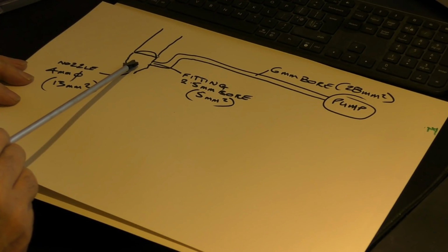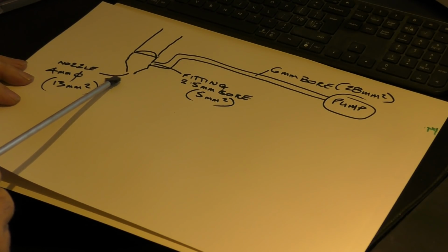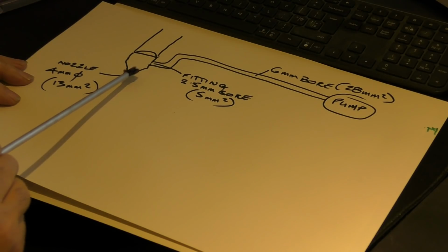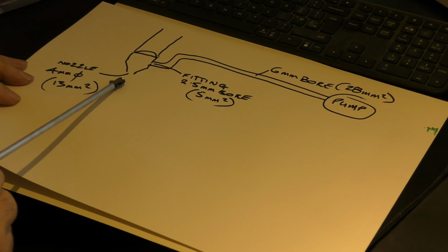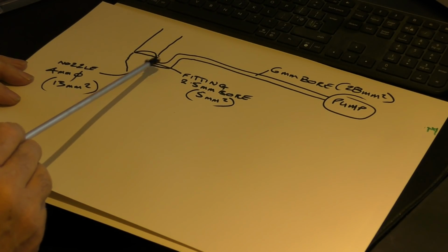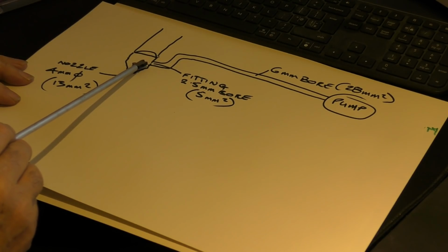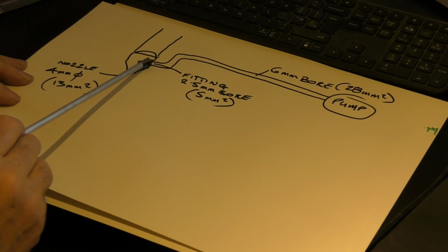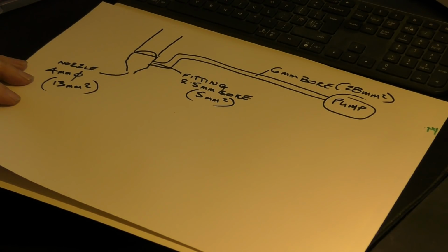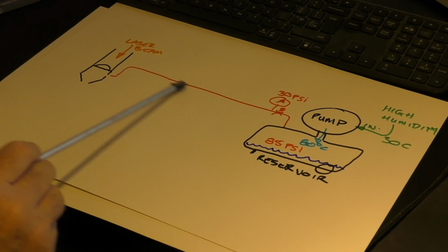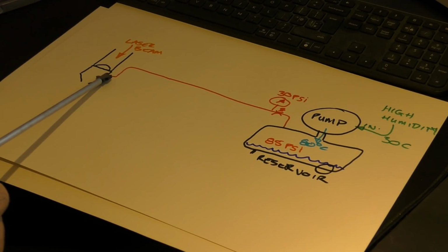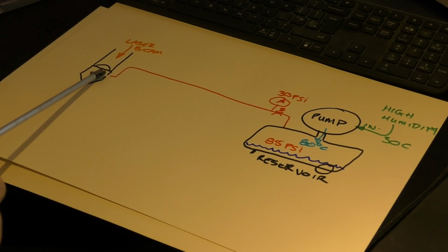And as it does so, it expands. And as it expands, it then has to come out of this orifice. Again, we're talking about flow. So it flows out of this orifice with only maybe half a psi difference between here and here, because this is so big in relation to this. This is the major pressure drop. And as pressure drops and air expands rapidly in this chamber here, it cools down, because it does the opposite of when you compress it. And it drops below the dew point of this supersaturated moist air that you've just supplied to that point there. And it's now producing condensation in this area here.